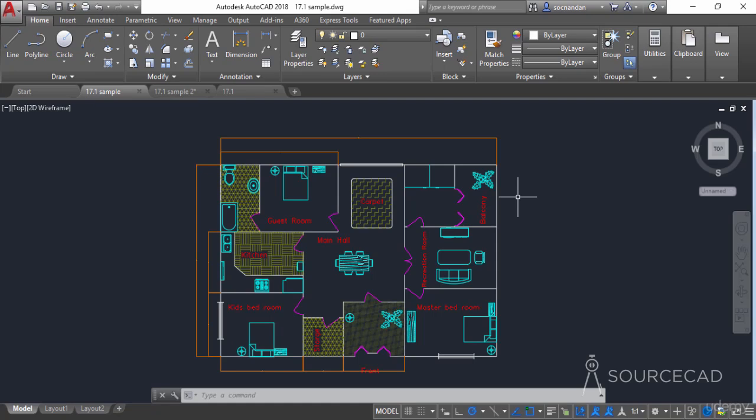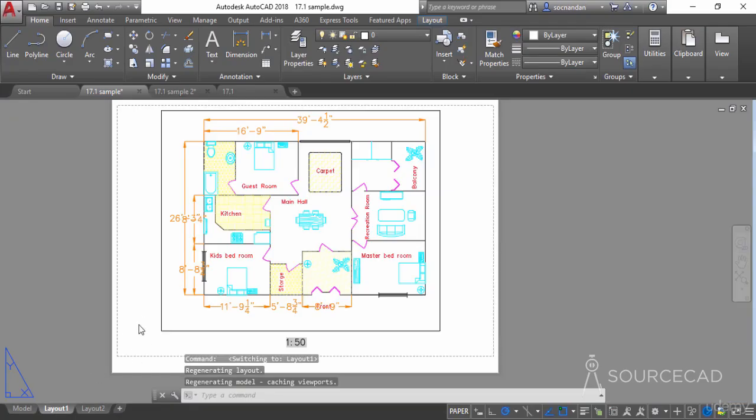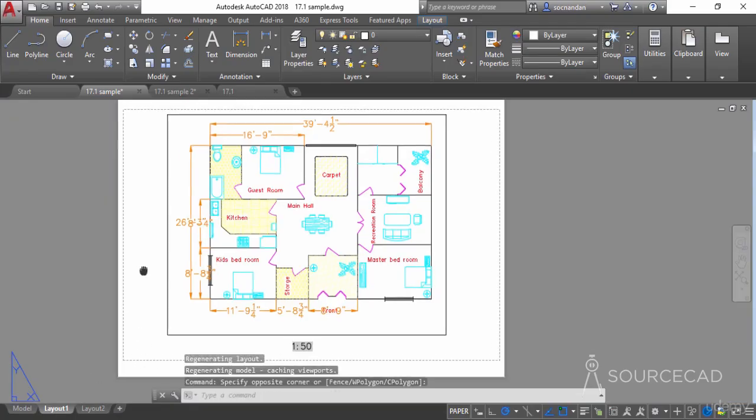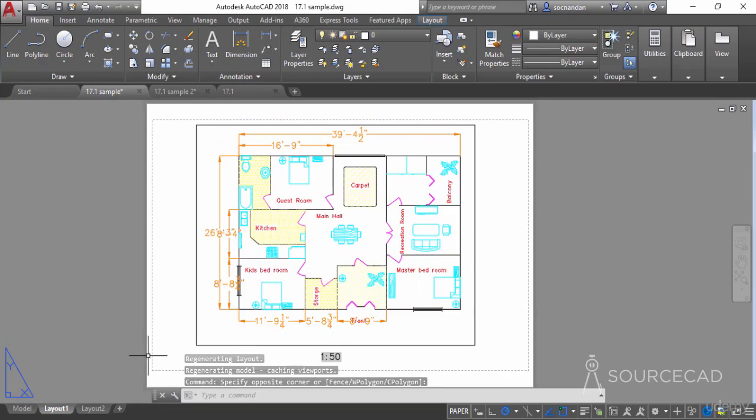In order to do that, what we do is we create layouts as we did here, and the size of this layout is A3. So we create layouts with a standard paper size, now in this case A3, and then we reduce the scale of the original object. Now when the scale is reduced, all the objects fit properly, and also the annotations can be added directly. Here you can clearly see that the scale has been reduced to 1:50. That means that when this drawing, which is on the paper, is increased 50 times, it will be equal to the size of the actual object.